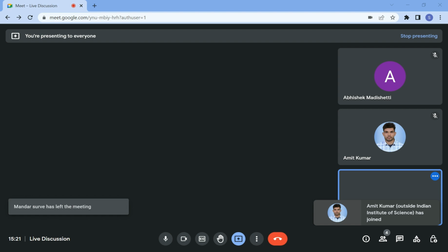So if point A is 20 above HP, it will be seen in the vertical plane, and 25 in front of VP, it will be seen in the horizontal plane. So let us mark this point A, 20 above HP here. This is point A, and 25 in front of VP, which will be seen as a distance in the horizontal plane. So this is 25 and this is my point A dash.